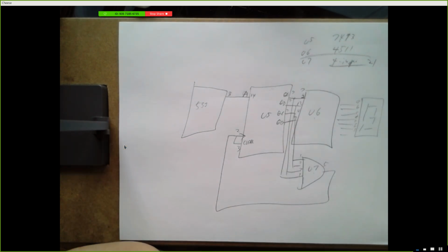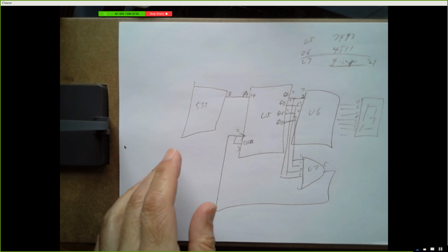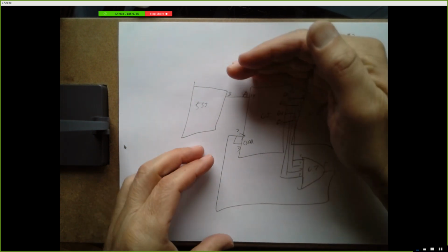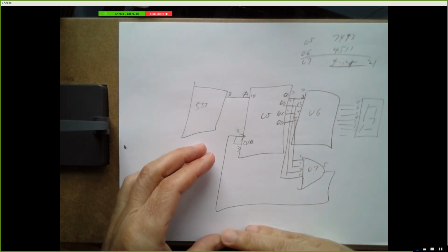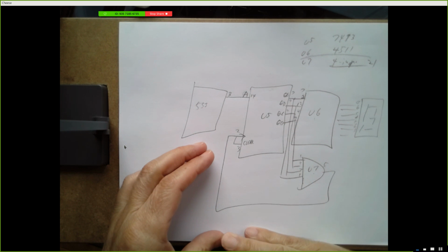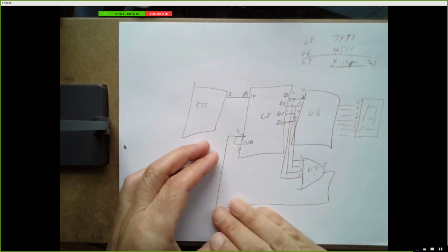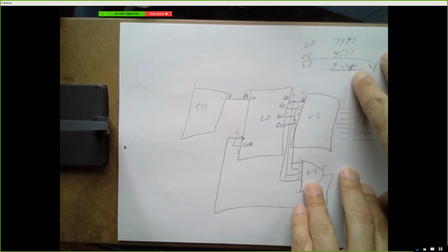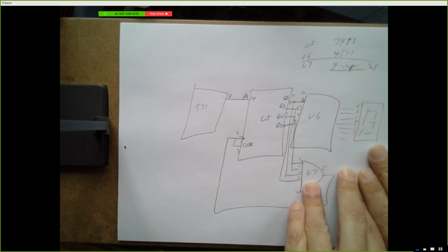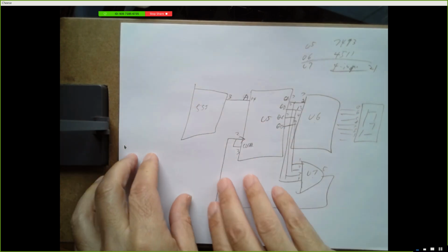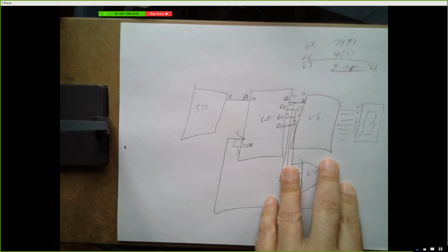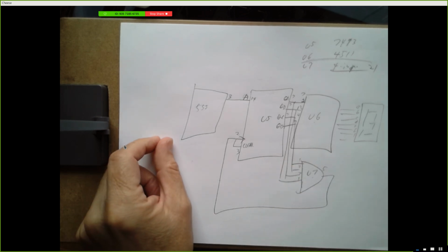They don't have to know about sum of products or 555s or anything else. They just follow your test plan. The test plan says, flip these two switches to off and this switch on, and you should see this LED light up and these LEDs turn off. They can flip the switches, look at the LEDs, say yes, that worked, and check it off.